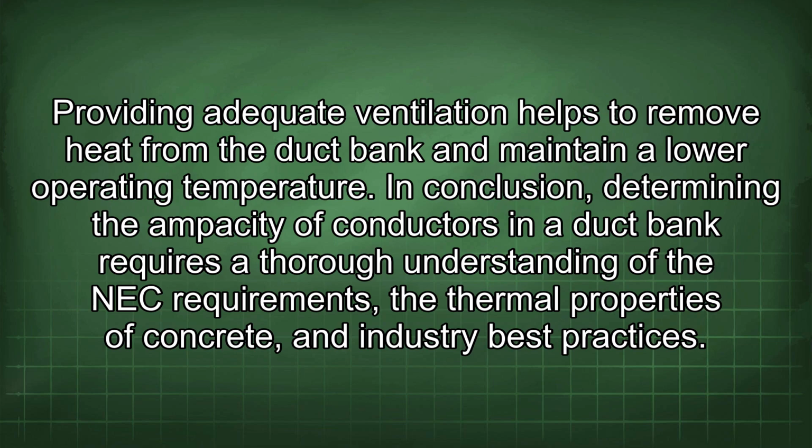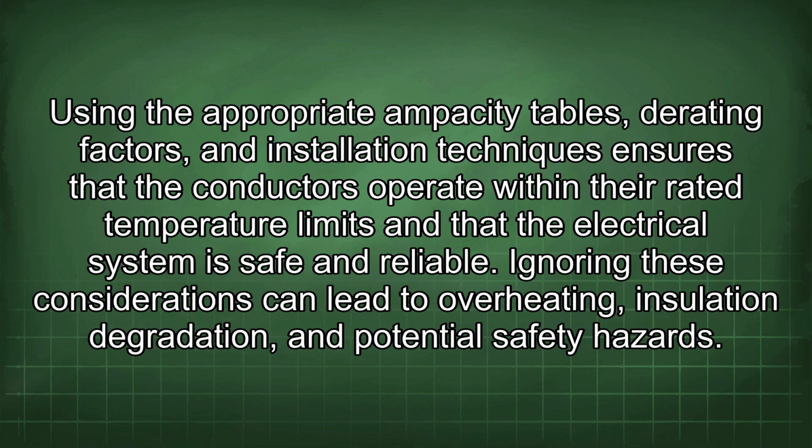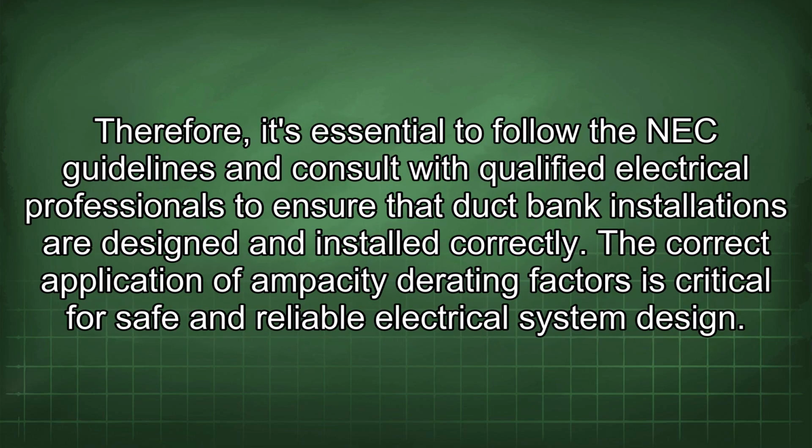In conclusion, determining the ampacity of conductors in a duct bank requires a thorough understanding of the NEC requirements, the thermal properties of concrete, and industry best practices. Using the appropriate ampacity tables, derating factors, and installation techniques ensures that the conductors operate within their rated temperature limits and that the electrical system is safe and reliable. Ignoring these considerations can lead to overheating, insulation degradation, and potential safety hazards. Therefore, it's essential to follow the NEC guidelines and consult with qualified electrical professionals to ensure the duct bank installations are designed and installed correctly.